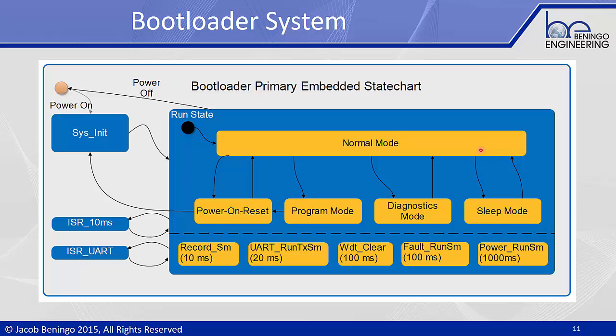We may have the ability to move into a low power sleep mode and move back to normal mode. Really, for today's purpose, what we're most interested in is being able to move from our normal mode into a programming mode, and then using that programming mode to update the firmware, and then moving through a power on reset process where we can then move back into the normal mode.